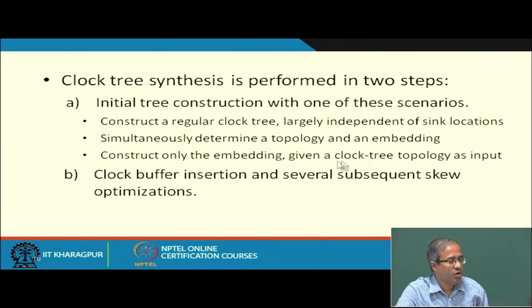We assume that a clock tree has already been built. Now we are talking about embedding, just like that grid structure I told you about, that I make a clock tree first, then I have a mesh or a grid, the clock tree is driving that mesh, and embedding means I have to tap that grid from appropriate points to take my clock signals, right? Okay.